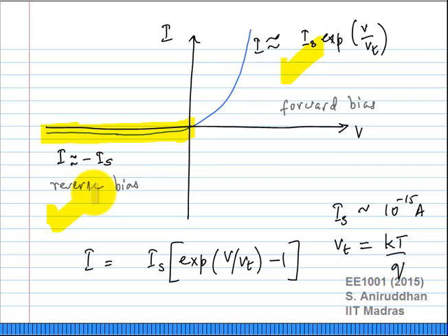Take the case of a resistor. You choose a certain reference direction for V and a reference direction for I. The resistor always consumes power, which is positive by our convention. Therefore the resistor operates only in the first and third quadrants. What is the characteristic of a resistor? It is a straight line occupying only the first and third quadrants. So any two-terminal passive element should occupy only one of these two quadrants. Now there are cases where you might have a diode, for example, which might occupy one of these two quadrants.